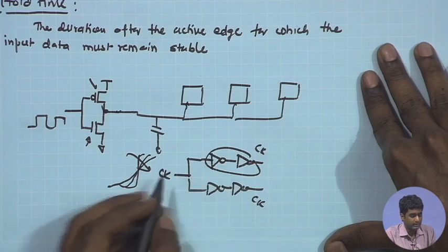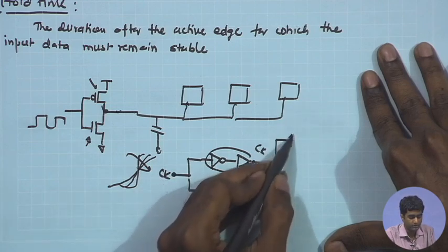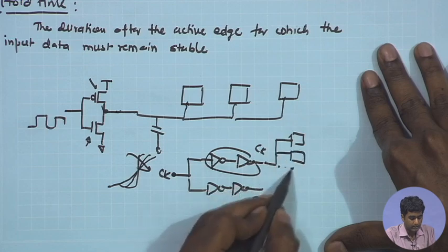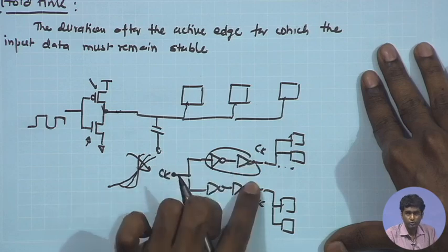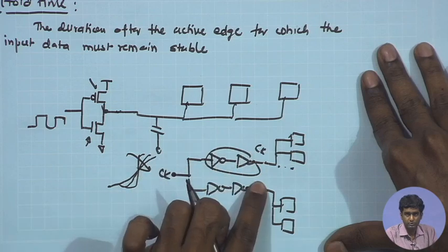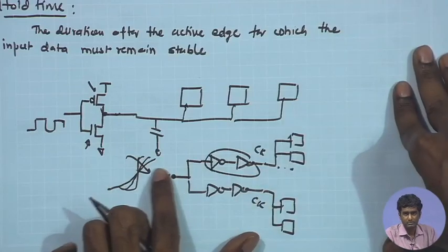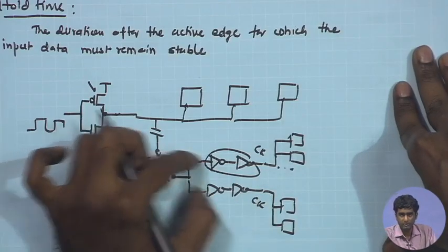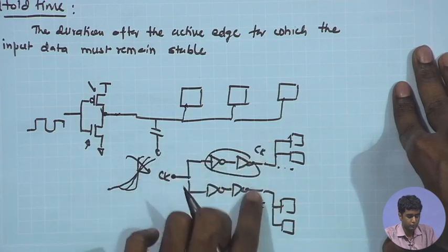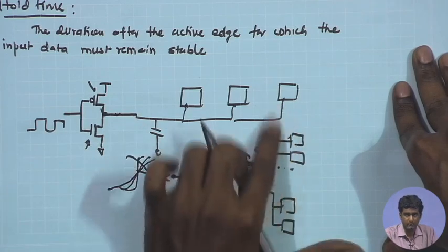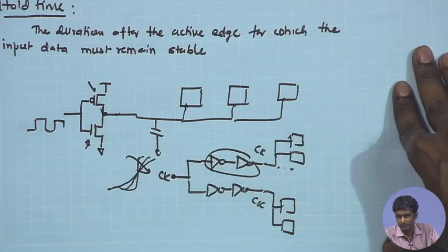So, in that case, rather than the one single clock driving too many blocks, I can have effectively two clock sources. So, I have divided the single source into two sources, and therefore their effective load capacitance will be halved. So, a digital signal or digital clock can always be buffered. You can have bifurcation, and then you can have two sources driving half the loads each, and as a result their fan out, their total load capacitances, will reduce.